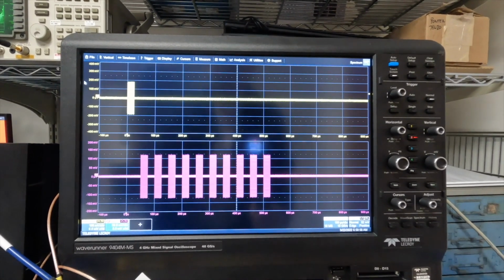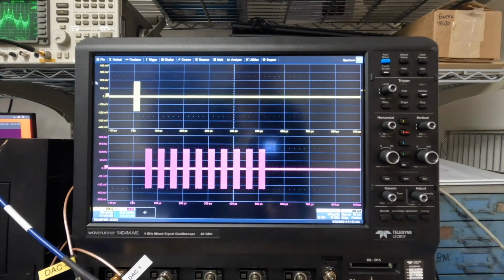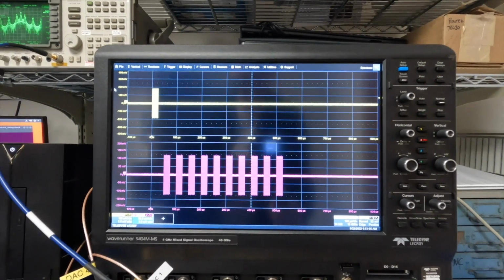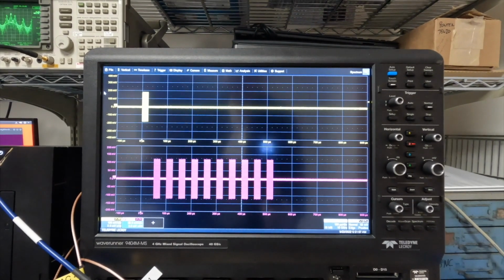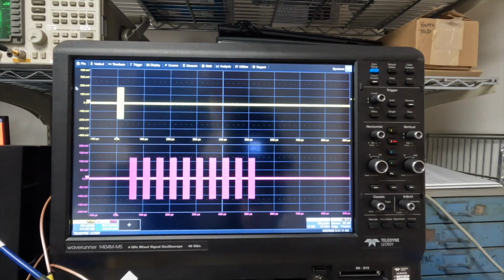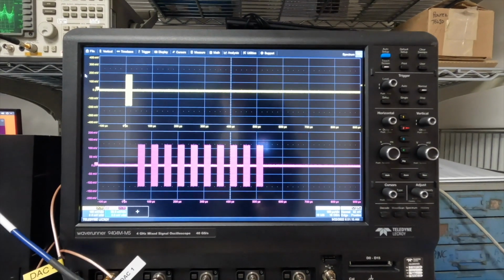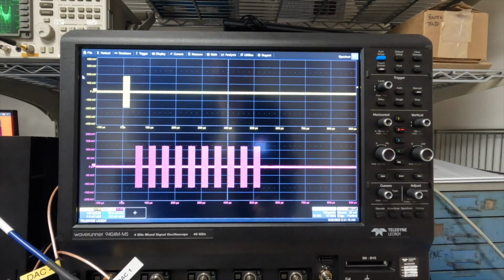Okay, so we've shown time control, number of multiple range false targets control, moving in and out in range, also coupling that with the velocity simulated to create a Doppler shift, so to make the range gate and velocity gate pull-offs realistic. And that's essentially it for today.